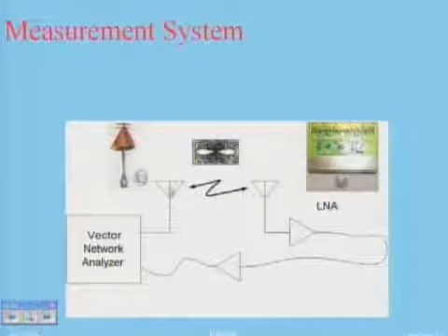Now, however, in there I had omnidirectional antennas. We were just using quarter-wave mast antennas. But here, they have a variety of antennas. One is the so-called bow tie antenna, like this. The other popular one is the cone antenna, like this one. This is a cone with a hat. These are two popular types of antennas for ultra-wideband.